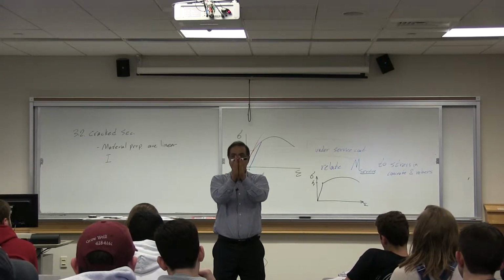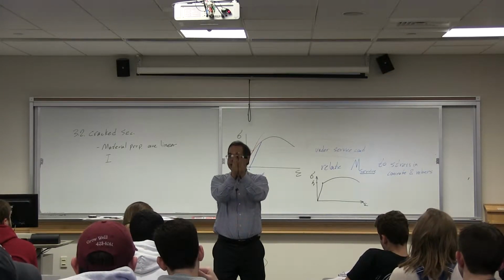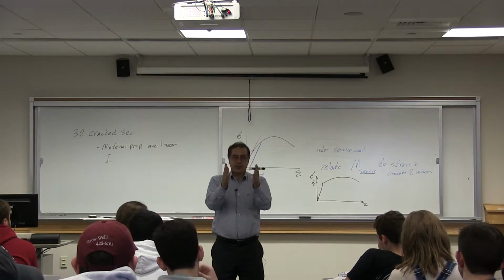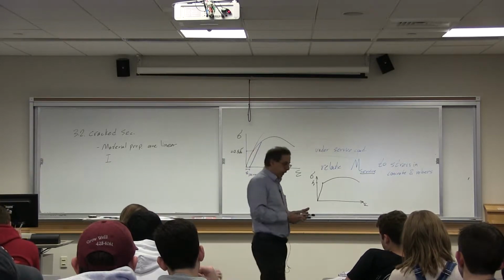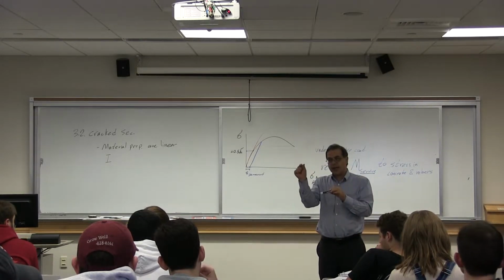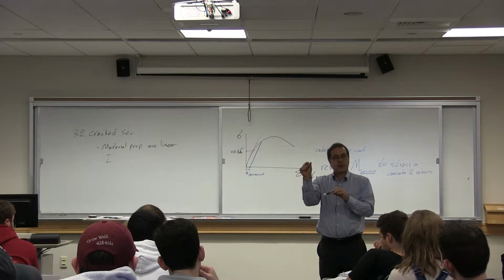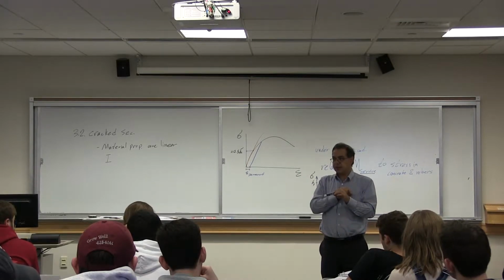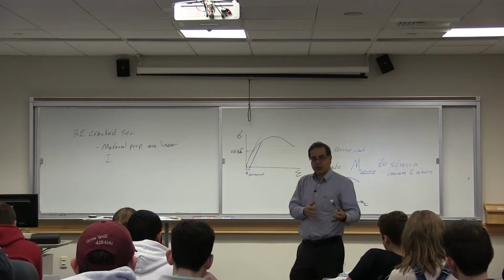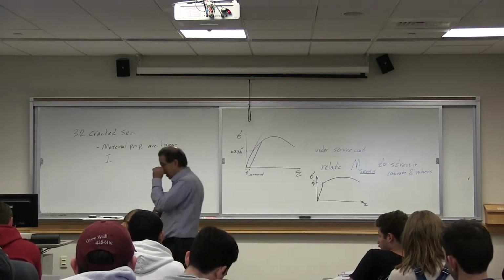The larger the strains in the rebar, the wider the crack. In fact, people who are more experienced with concrete, based on the size of the crack, can give you a best estimate of what's the stress in the rebars. The wider the crack, the larger the stress in the rebars.